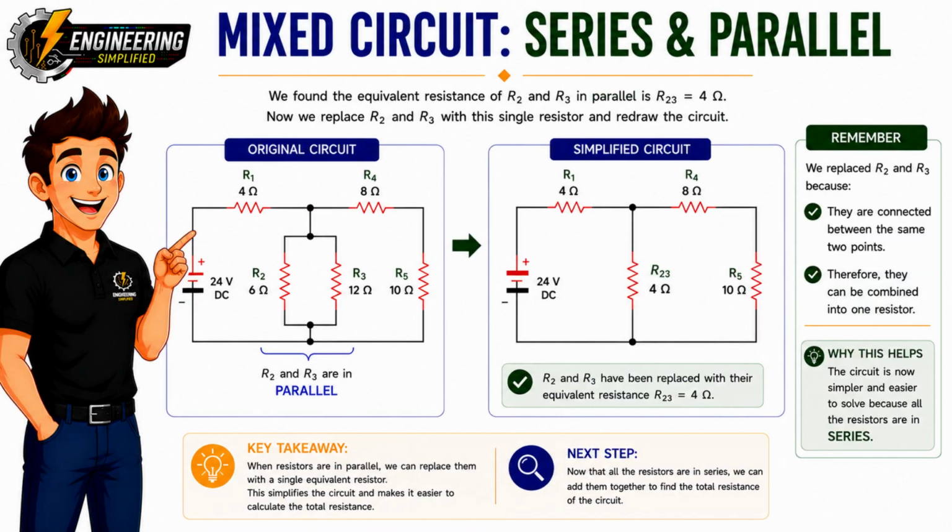We've successfully found the equivalent resistance of the parallel branch. R2 and R3 together are equal to a single resistor of 4 ohms. Now we can redraw the circuit using this new equivalent resistor. Notice what's happened. The two resistors in parallel have disappeared and have been replaced by just one 4 ohm resistor called R23. This new circuit behaves exactly the same as the original one. We haven't changed how the circuit works, we've simply made it much easier to analyze.